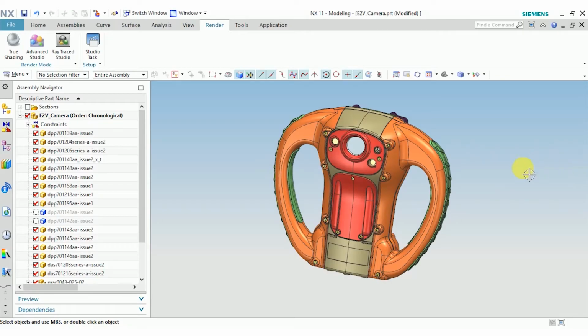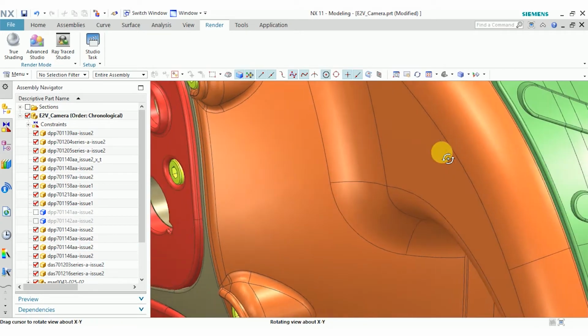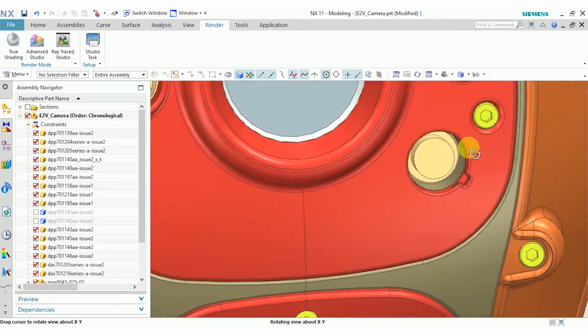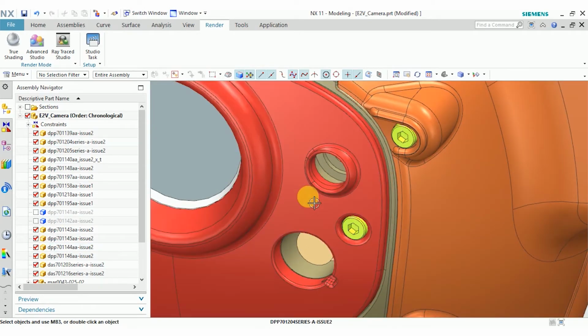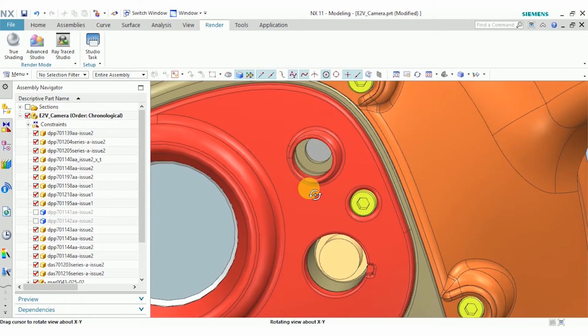For large parts and assemblies, you may want to work in a small area. Once you zoom in, if you just try to rotate the part, the area you want to work on might rotate out of the view. The trick is to hold down your middle mouse button, wait till it highlights a face, and it'll rotate about the highlighted face instead.